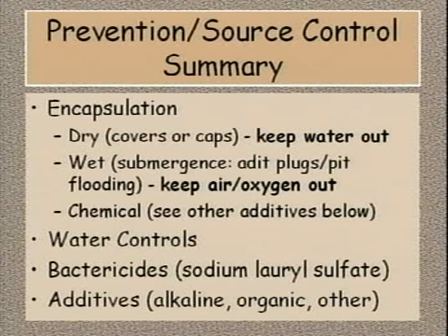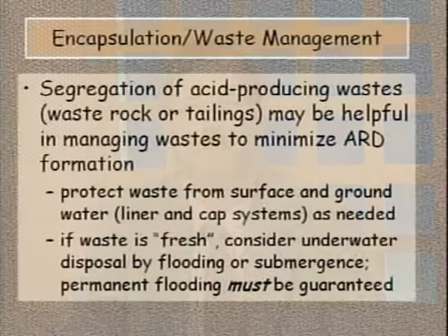Water controls include diversions of both surface water and groundwater, and the active ingredient in the commercial bactericide for ARD control is sodium lauryl sulfate, a common soap ingredient. You probably used it this morning when you took a shower. We'll discuss additives and amendments in more detail, but this approach can be problematic when you consider the huge volumes of mine waste at a typical metal mine site. For this approach to be economical, the amendment has to be free or inexpensive and close by to minimize transportation costs. Let's talk about macro encapsulation first.